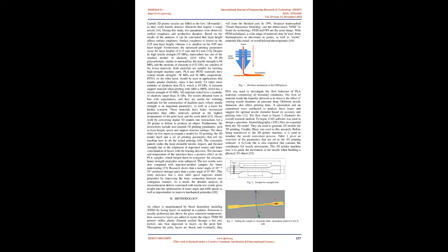The softness of brass is fine for printing common materials such as PLA and ABS but becomes problematic when printing exotic materials such as glow-in-the-dark PLA or metal-enriched filaments. A 3D printer's nozzle gradually erodes as a result of the continuous extrusion of filaments containing hard particles. With time, this distorts the opening and inner dimensions of the nozzle, reducing the consistency of what is extruding out of the nozzle at any given moment and affecting the quality of prints. Due to this, 3D printer nozzles made of harder materials are preferred for such applications.